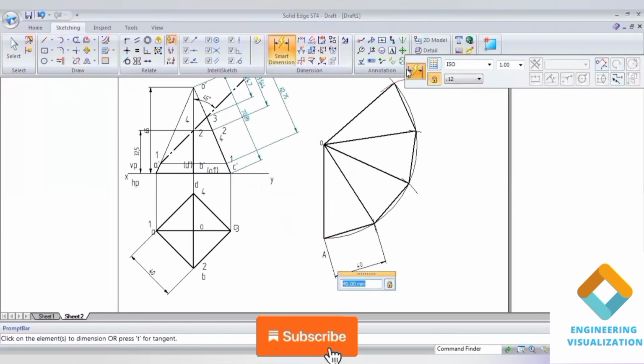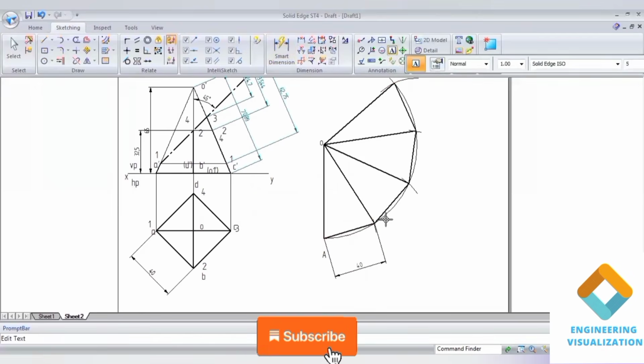So the dimensions we can measure and give the naming: capital B, capital C, capital D, and capital E, and A again. Now at the cut points we should mention the dimensions which I have already measured for the slant edge. For A1, we should cut an arc of the same length. Similarly for 2 and 4 it will be the same length, and for 3 it is the length which we measured. Okay, go to arc by center and type that same radius.